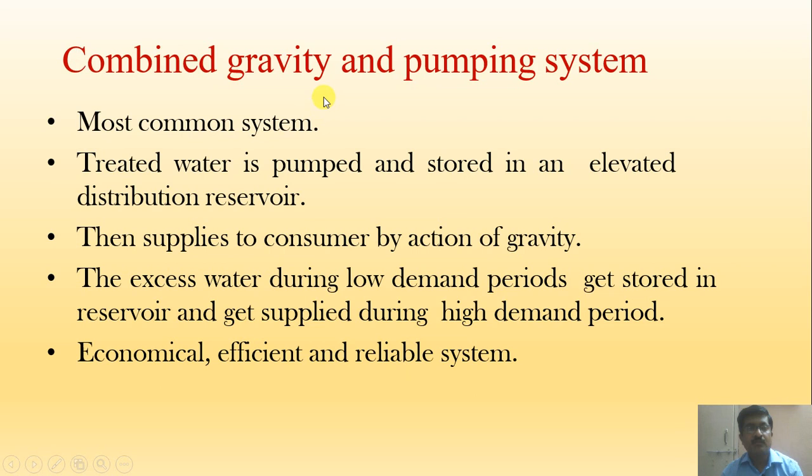Next one is a combined gravity and pumping system. It is the most common system, as I explained earlier. Treated water is pumped and stored in an elevated distribution reservoir, then supplied to the consumer by action of gravity. The excess water during low demand periods gets stored in the reservoir and gets supplied during high demand periods. Economical, efficient and reliable system.